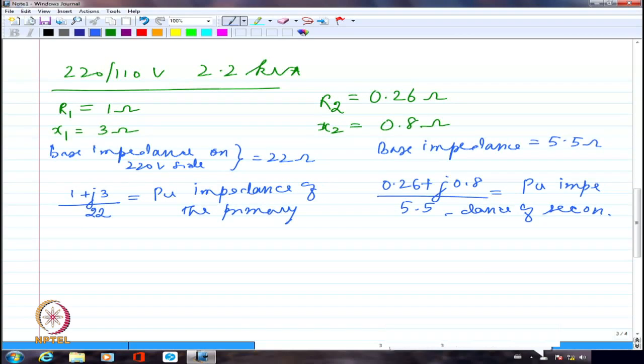calculations correctly. If I look at a transformer, normally the voltage regulation has to be less than 10% in most of the cases. So voltage regulation, again what we are calculating is on a per unit basis, because we are dividing it by rated voltage all the time. So we get the drop and we are dividing it by rated voltage. Because we do that, again we are able to get an estimate whether the voltage drop is less than 10%. That means whether I have done everything correctly or whether the transformer is good enough. All these things I would be able to get a feel for by observing. That is one of the major advantages of using per unit notation.